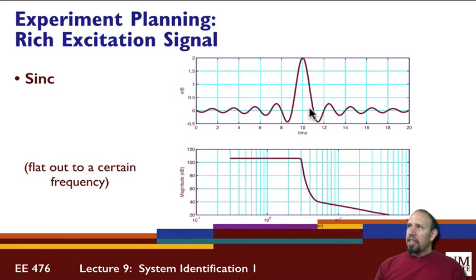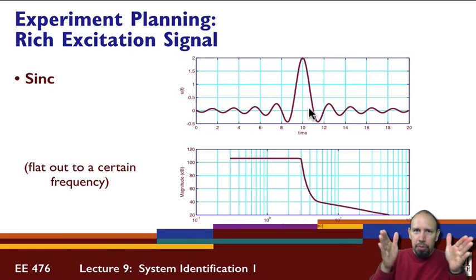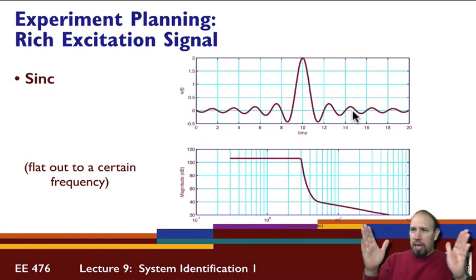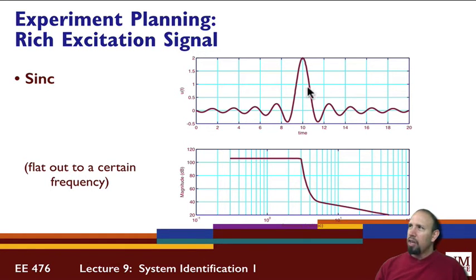Now, it turns out that if you take the sinc function and compress it in time, that basically expands the frequency response out. So I could expand this frequency response all the way out to the Nyquist frequency by compressing this sinc function down. But when we sample that sinc function, if we compress it all the way down, we'll basically get something like a delta function. We'll have 1 at this value and zeros everywhere else. That's a very simple function to implement. You just have all zeros and then a 1 and then all zeros.